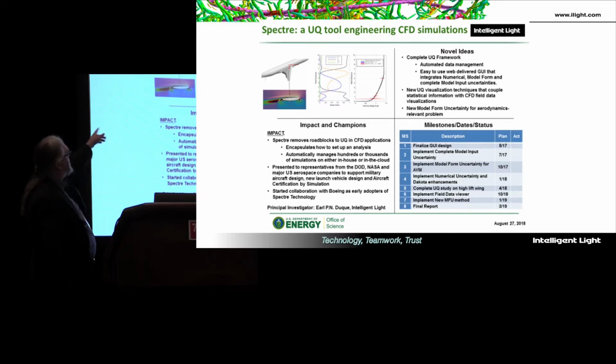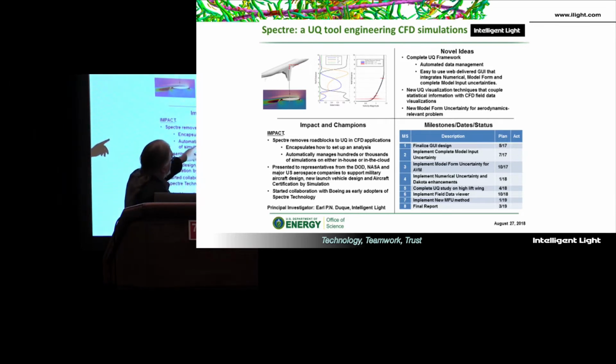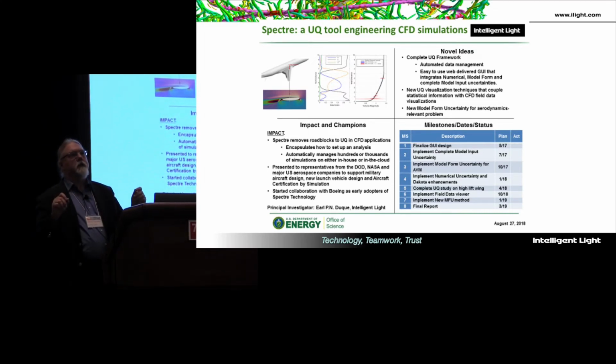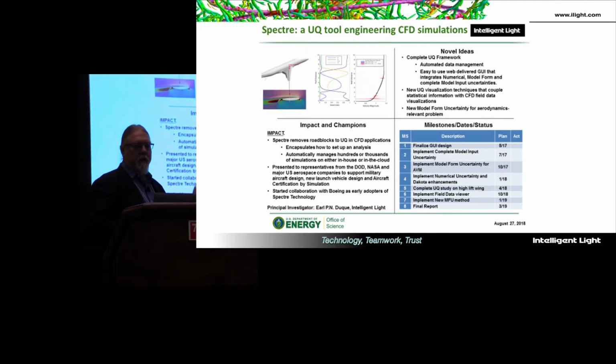And you can't really see it in the fuzzy picture up above, but this is the velocity magnitude going vertical to the wing. So it's 0 at the wing, and it increases with the typical curve going up, that black line. And there's little red smears. And those red smears are areas where the uncertainty is higher because of the turbulence model transition. It's very interesting stuff. Automated. Our idea is that engineers will, in the future, if they have to get a 90% confidence interval, have an easy way to do this kind of stuff without manually writing Python scripts and everything. So this is kind of a cool thing. We're just starting to launch this now.